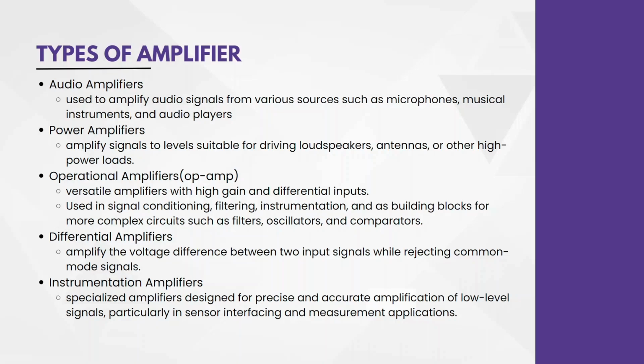But these amplifiers have high gain and their inputs are different. Differential amplifiers, as the name says, will amplify the difference in voltage between the input signals. And instrumentation amplifiers are specially designed amplifiers that are very precise and accurate, mainly used for low level signals.